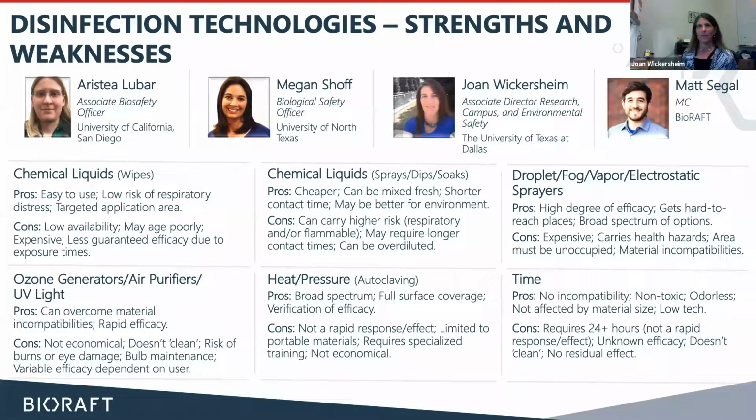I think one of the things we had to consider is that when you change the MERV rating on the filters, you're putting more back pressure on your fans and your systems. And we have a lot of systems that run 24/7, especially in our research buildings. They're already taxed as far as mechanics go. We bought these systems hoping they would last, I don't know, somebody thought they were going to last 10 years. They're barely lasting 3 because you think, oh, it's an office building, we're going to run it for 8 hours a day and then shut it down.